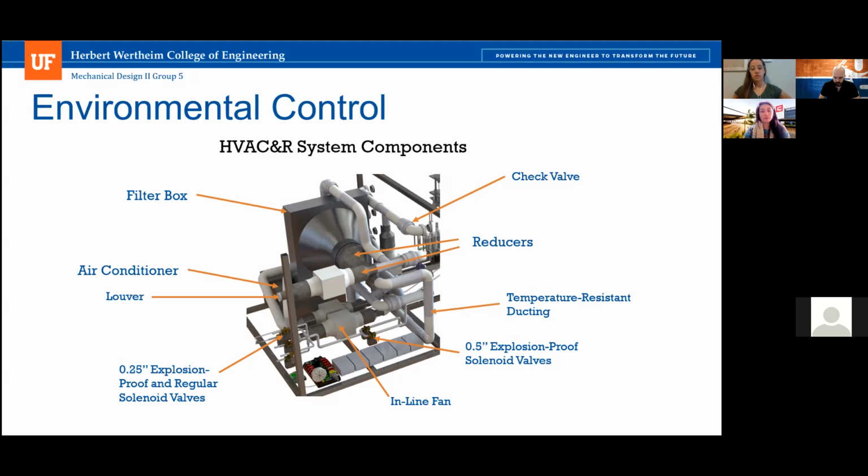Now, for gas management, there are 5 ends of tubing that stick out of the device that can be hooked up to any gas tank. Explosion-proof solenoid valves were utilized for tubing for combustible gases, of which there are 3 predicted in our customer needs, as well as the 2 tubes that lead to the chambers, as it has been proven in industry that previously experimented solenoid valves that were not explosion-proof tended to explode when exposed to combustible gases. Next slide.